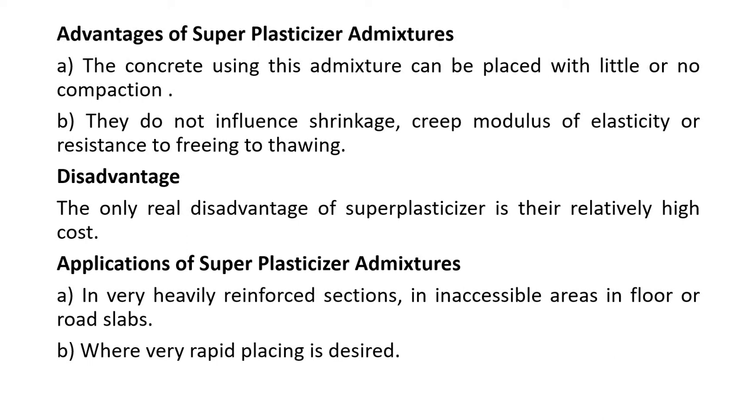Disadvantage: the only real disadvantage of superplasticizers is their relatively high cost. Applications of superplasticizer admixtures: very heavily reinforced sections, inaccessible areas, and floor or road slabs where very rapid placing is desired.